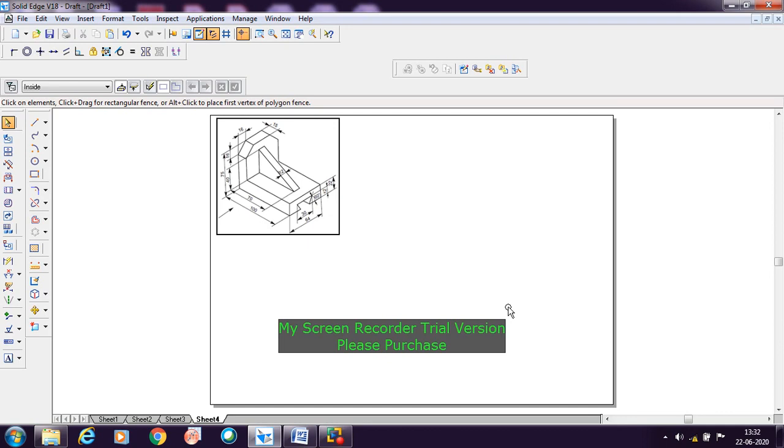And in order to select the views, the top view, front view, and then the side view, it's very easy, we can draw the top view and front view. And in order to select the side view, we'll be having the doubt. For the side view we need to take the direction in which we see the object, in this direction or in this direction here. So for that, we need to see the condition that in any particular view, we need to get the maximum details of the object. In that way we need to select the appropriate side view here.